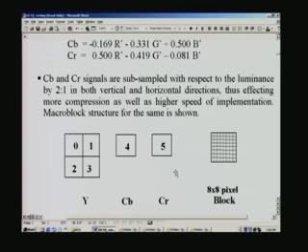Each block processing takes the same time. So that means, when compared to a monochrome, for which we need only 4, for processing true color we need 3 times that. So if you want 3 times the speed, sorry, 3 times the time you require, that means the throughput is just 1/3 of what you get in monochrome. In other words, resolution of the picture will get hit, so you will have to scale it down by a factor of 3. So are you clear about this? If you process more blocks it takes more time, that is what I am trying to say.